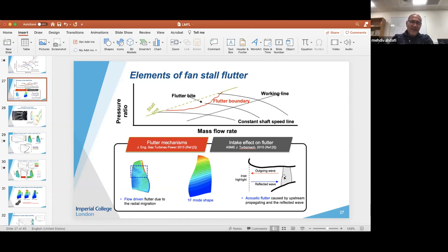I think for flutter, this is a personal viewpoint, if you can get your base mean flow correctly, then you can use any linear code to predict your flutter. I think we get very similar results. The whole idea is how are we going to get the steady mean flow correct? And that comes to turbulence modeling, or whether we can run high fidelity CFD to get your mean flow. From my personal experience, the hardest part of getting flutter correctly is to get your mean flow correctly.